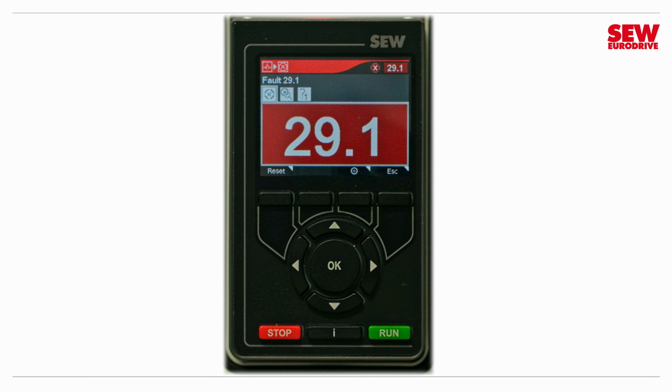And what I notice right away, instead of going to the status screen, we have a fault. Well, I did this intentionally because I wanted you to see how the keypad handles faults. This is a limit switch fault. I just don't have my limit switch turned on, which is why the fault appeared. Let's see what information we get when we have a fault when we're using our keypad.